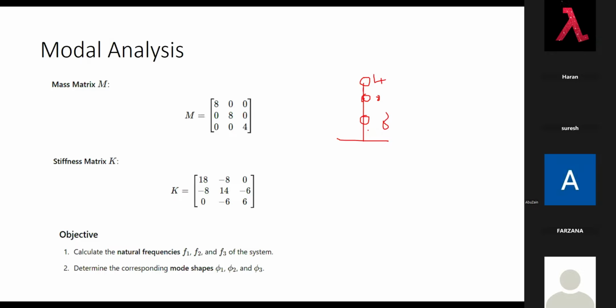And this is my K, K effective here, K effective here. So this K we also need to calculate somewhat differently. We need to take K1 plus K2 to get the effective at this bottom. I will say this later. Now, how to develop this mass matrix and K matrix, we'll do in the next class. Now, mass and K matrix are given.